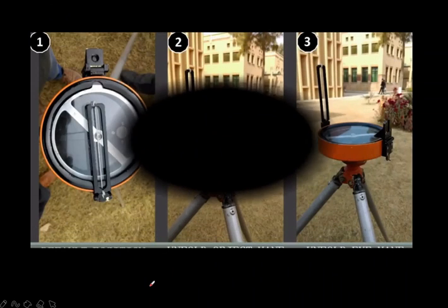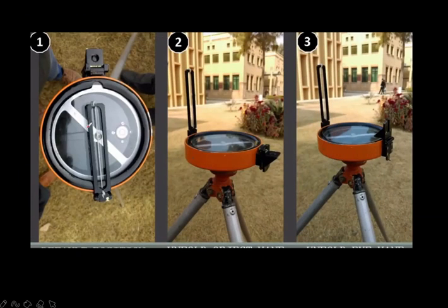So next comes, see, one minute. Next is your prismatic compass top view. This is the eye vane, this is the object vane. Okay, this is the tripod stand. See, this eye vane is open now. Now it is in position. Whenever this eye vane is rotated like this, it will come in position, and this is the slit where we sight the object which is to be sighted.